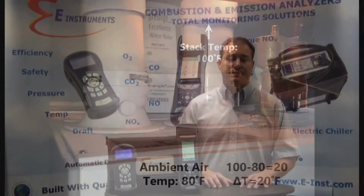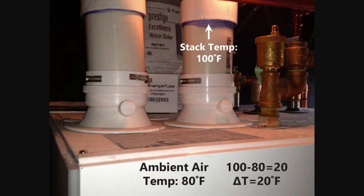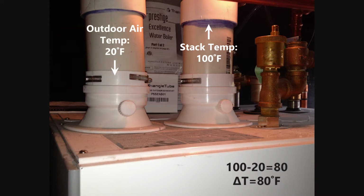See this example. If we use an analyzer the same way we do on an atmospheric system, then this is what we could see. Here we have 100 degrees Fahrenheit in the stack, minus the ambient air temperature of 80 degrees, gives us a delta T of 20 degrees Fahrenheit. However, this is not necessarily true, because we are actually using cooler outdoor air temperature for primary air for the combustion.